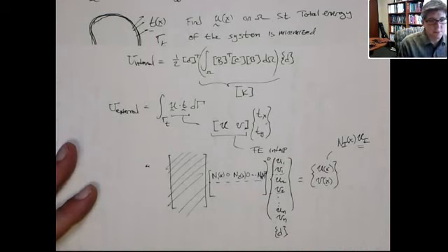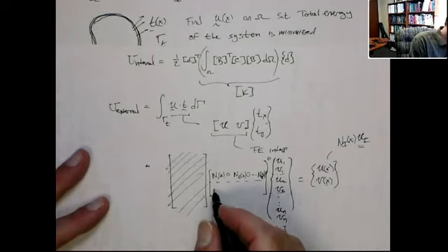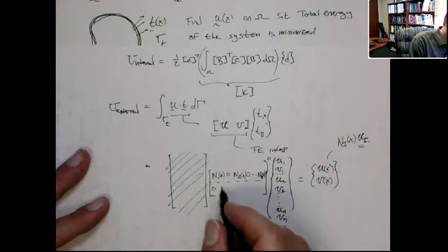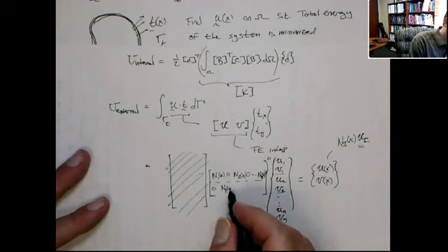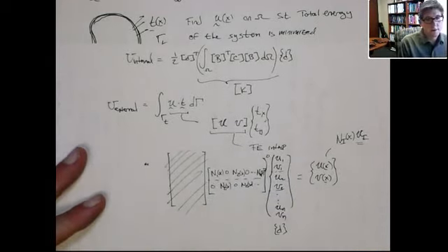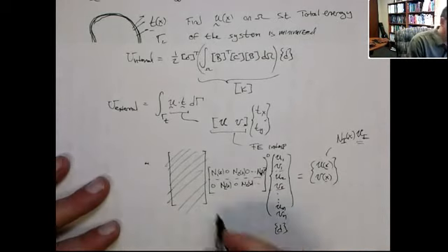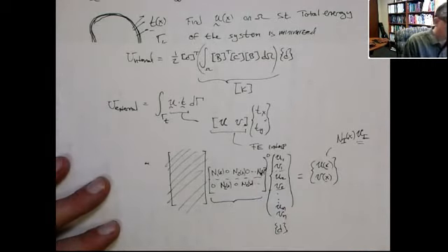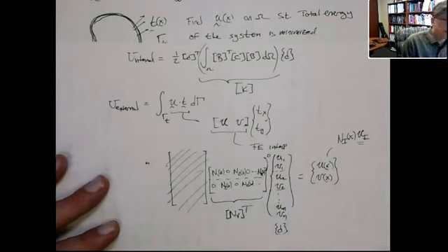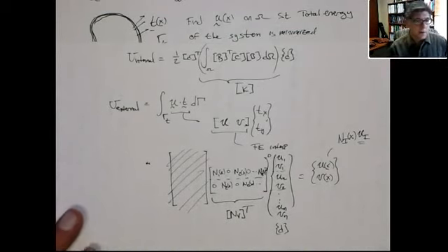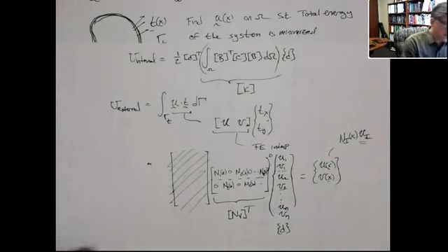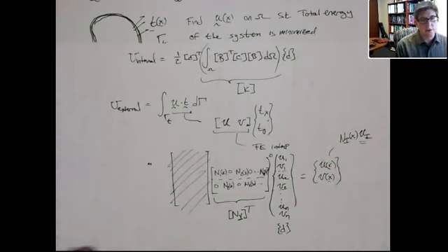I didn't leave myself enough room. I'll rewrite it. Likewise, this bottom row is what gives you the y degrees of freedom, so everything involving the x's should be 0. But I'm going to call this matrix NV transpose. It's something like the shape function row vector, but it's such that it gives the displacements of the vector field. So I have that little v there.